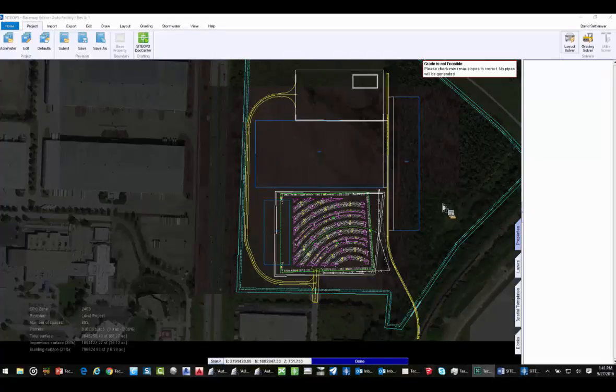All right, got another question for you here, David. What is the content that exports to GeoPack or InRoads: horizontal and vertical alignments, intersections, terrain, or just line work? For now, it's just doing line work. We're working to make the export a lot more robust for the MicroStation-based products. So right now it's more of the line work, the surface, some meshes, some things like that, and that's what it's exporting at this point. If you are an Autodesk user, it exports a little bit more. Just from our past history, we've had a lot of Autodesk users, so you'll get a little bit more output in a DWG file.